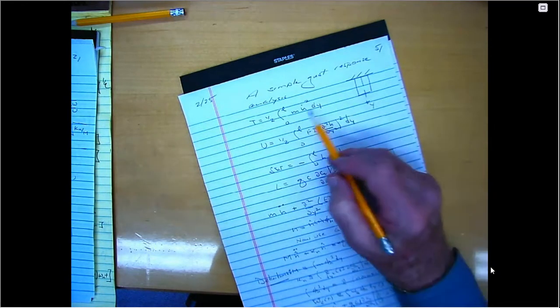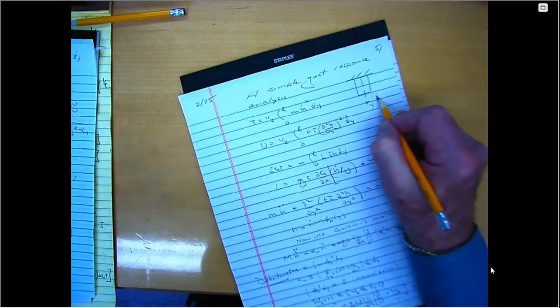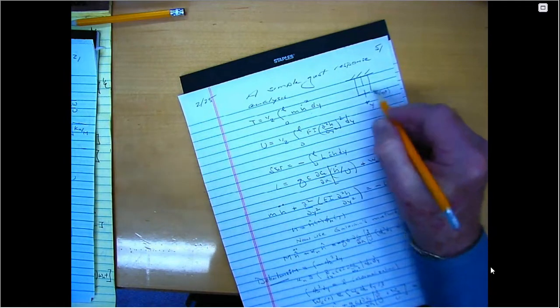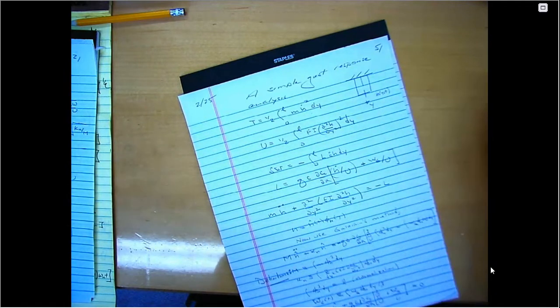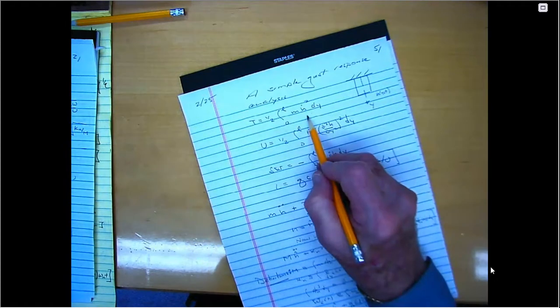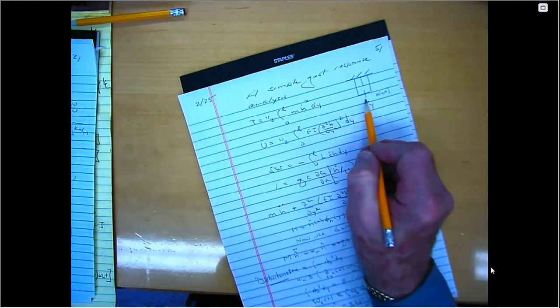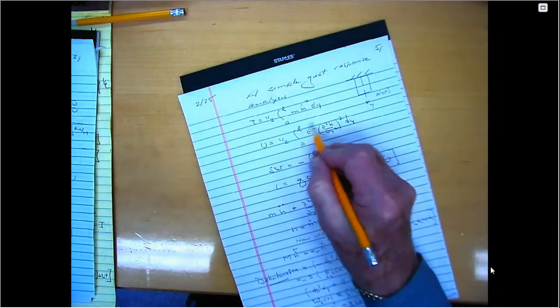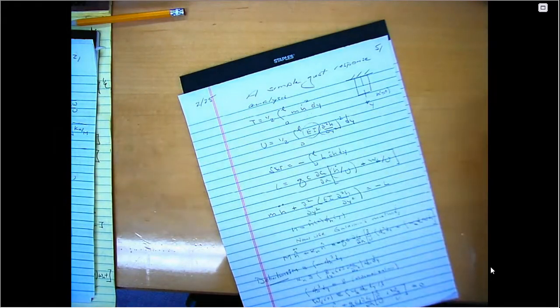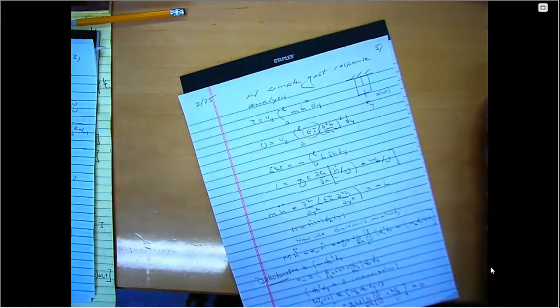In this example, h(y,t) is the bending of this elastic axis. And this is the kinetic energy of this wing if it's just undergoing simple bending. This is the potential energy, where EI is now the bending stiffness as opposed to GJ, the torsion stiffness.